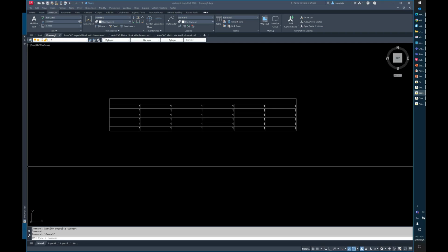Would setting the DWG units, like you previously showed, fix this, or is that another issue? The DWG units may actually fix that because, again, it's going to take a fraction of that. Normally we can display up to 9 decimal places in AutoCAD, but AutoCAD, from what I remember correctly from past years, is mathematically correct to at least 14 decimal places, and I think that number has actually increased. So as long as there's that little smidge of decimal and it's not a perfect 0 out to the maximum number of decimal places, it should still read it the way you think.